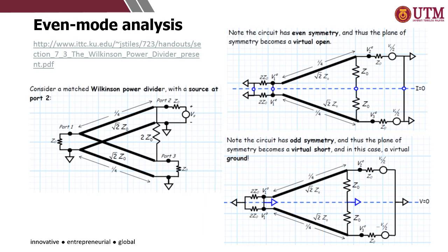Okay, the even and odd mode analysis is used to analyze the S parameter for the Wilkinson power divider, in which the input port can be represented by an equivalent circuit.